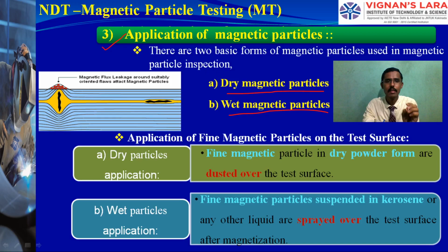But it is given there itself. So this is how it will be. Maybe the red powders are sprayed, and the flux lines are in the same uniform direction. The defect which is perpendicular to the flux lines will obviously obstruct the flow. So some particles gather, and some variations will be there in the flow of the magnetic field.